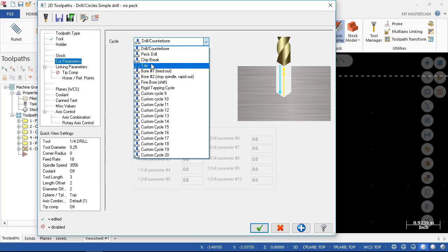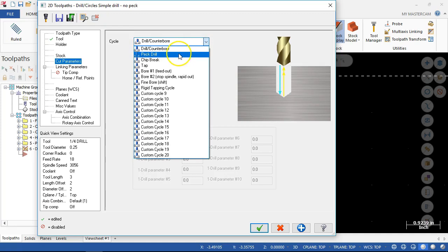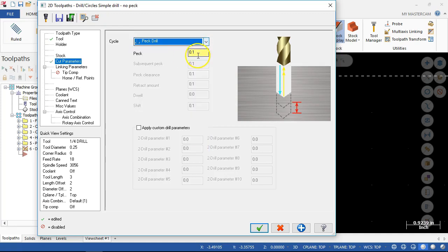So I'm juggling numbers in my head all of a sudden. So drill is, wow, we're really trusting this. We have a parabolic. We're going to jam it straight through the part without a center drill. Not likely. All right, if we're going to forego the center drill, then we're going to peck drill. We'll go by materials. So if we just did half D, I might try half the diameter, 125. All right, so that shouldn't be too far out of the realm of possibility.